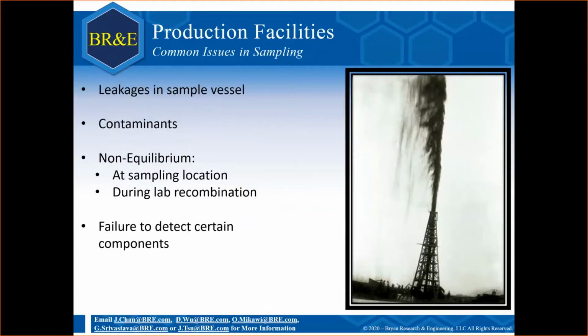And the common issues across both types of samples is, after you've taken the sample from a downhole system, for example, you could have leakages. Any leakages in the sample mess with the thermodynamics and the equilibrium of the sample. With a poor thermodynamic equilibrium in the sample, we cannot get an accurate representation of the contents of our system. We could either have our oil be too heavy or our oil be too light.